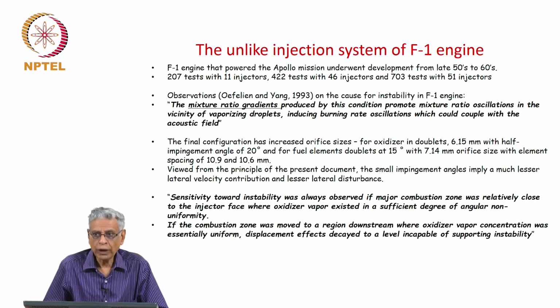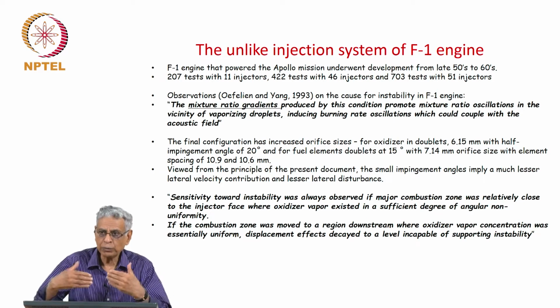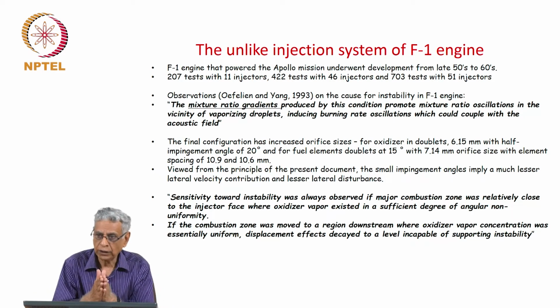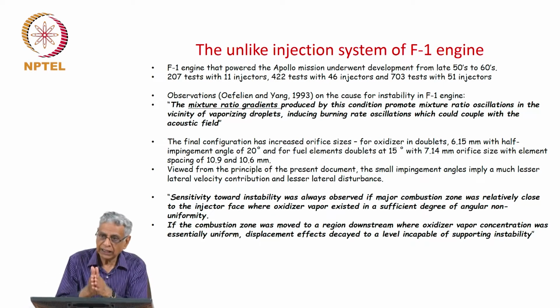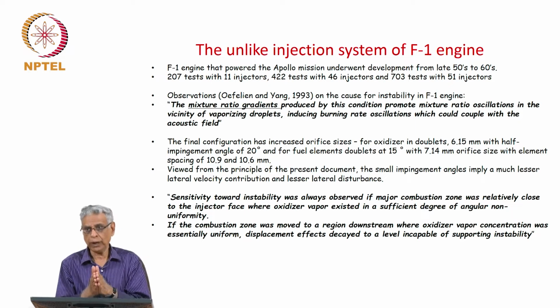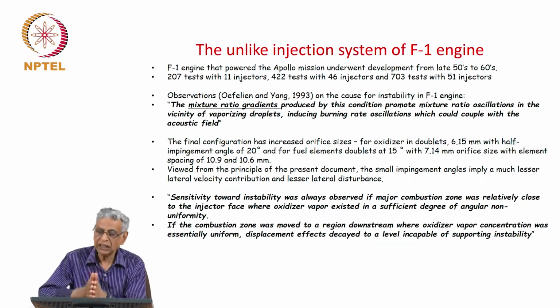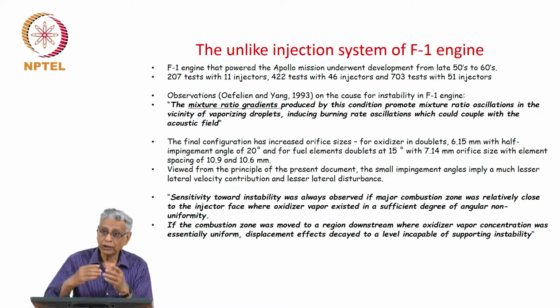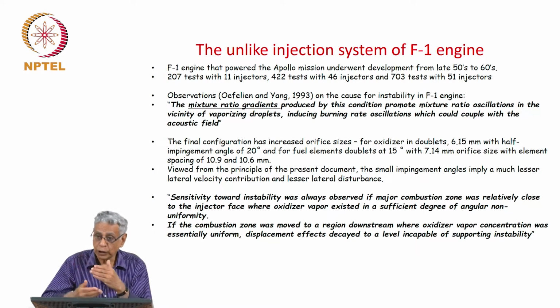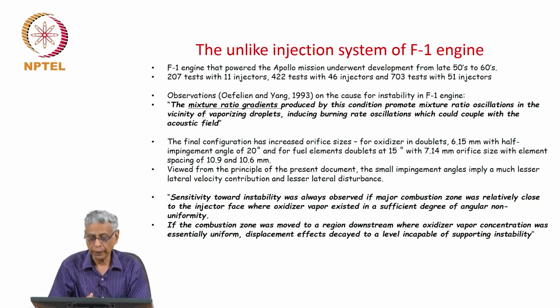Suppose injector hole diameters are small, impingement occurs closer to the injector face and the interaction will be much more intense. The heat release starts closer to the injector face. Now, do remember, when the sprays interact, there will always be a spray distribution around, with a mass flux distribution which can be variously oriented.